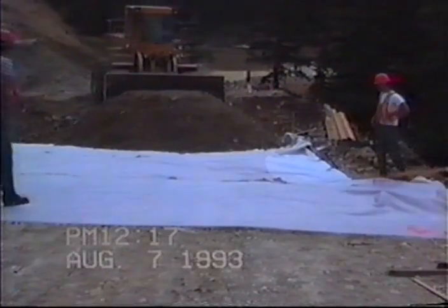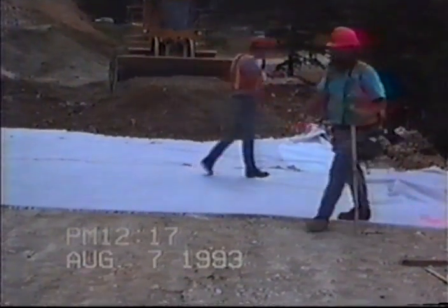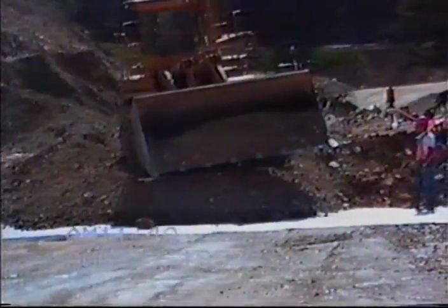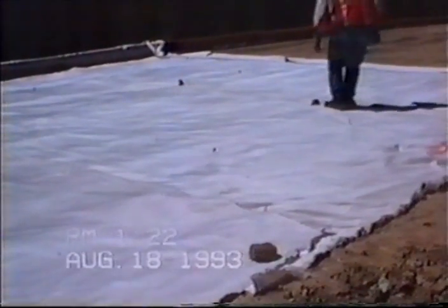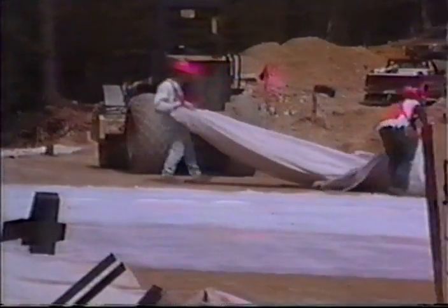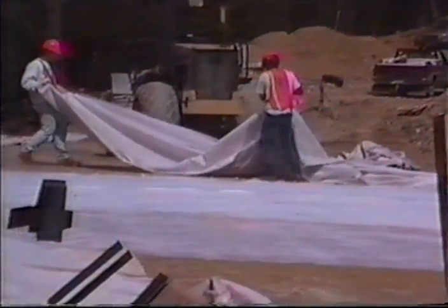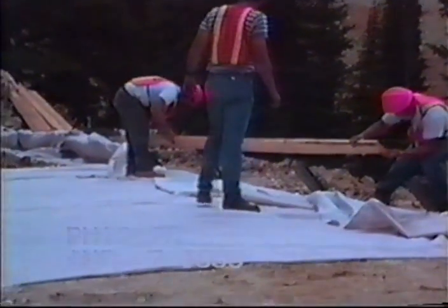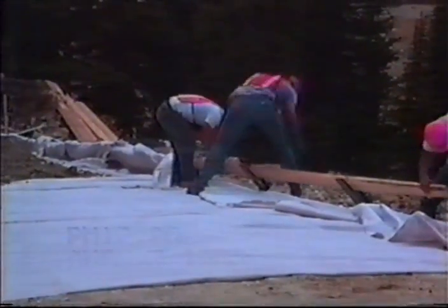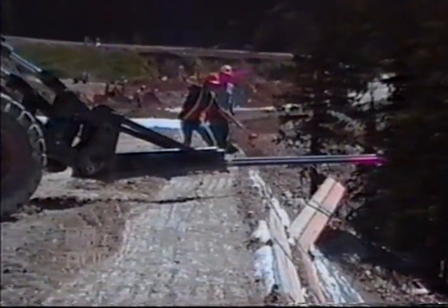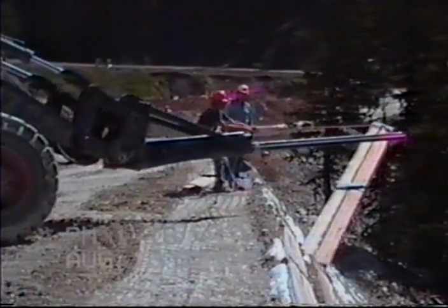The embankment was constructed using 300-millimeter layers of backfill from on-site roadway excavation. A geotextile composite reinforcement material was placed between each soil layer with its strongest direction perpendicular to the embankment alignment. Construction equipment was not permitted directly on the geotextile. A temporary form was used to support the face of the embankment during construction. This was done to minimize movement during compaction and to maintain the angle required on the face of each lift.